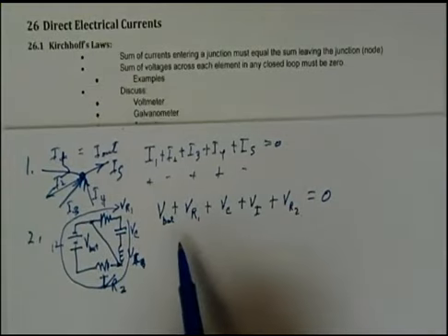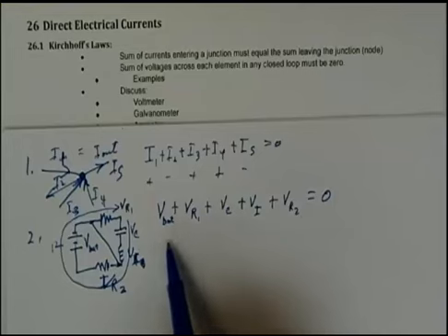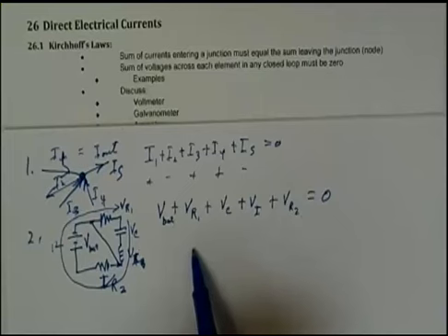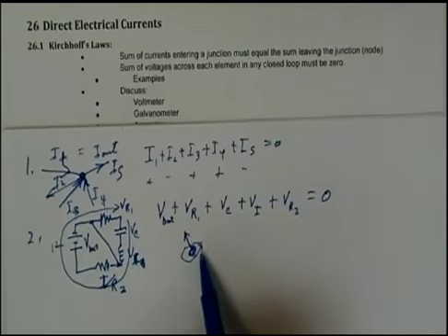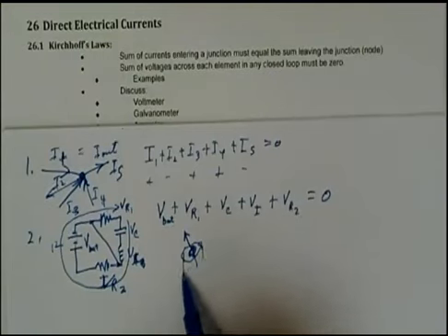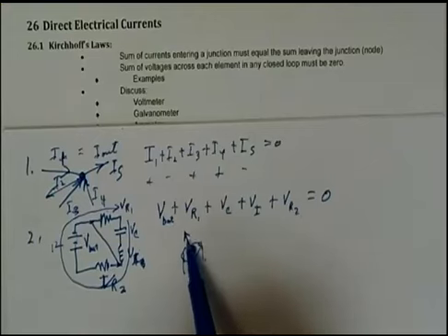There are two instruments that I won't go into great detail on. They're basically built upon the concept of a galvanometer. A galvanometer would have a small coil with a hand that goes through it and another coil that came around the side of it. When a current flows through this coil, it causes this coil to have a magnetic attraction to this other coil, which has a constant voltage through it. And the hand will swing over here.